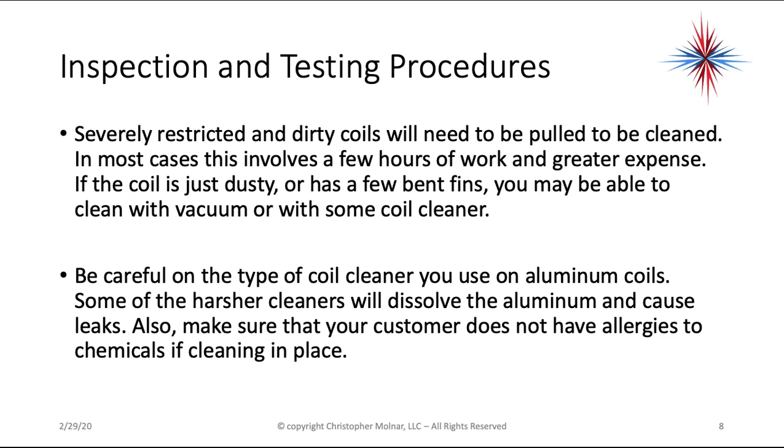Also make sure that your customer does not have allergies to any chemicals if you're cleaning in place, because you can't rinse off all the dirt, all the chemicals you used out of these systems if you're cleaning in place. People have chemical allergies, specifically to chlorine and some of the other sulfur-based chemicals, and you just got to be aware.